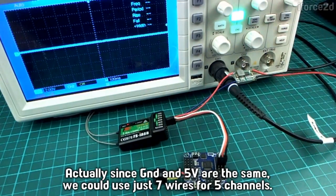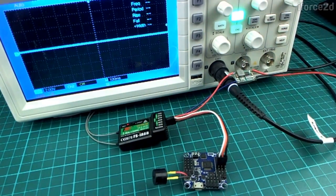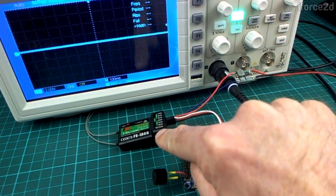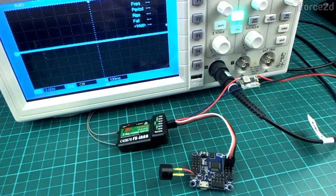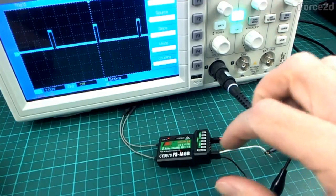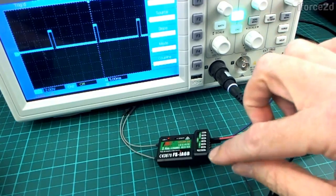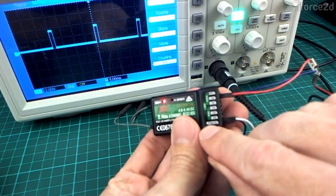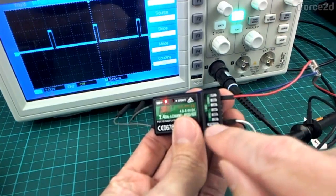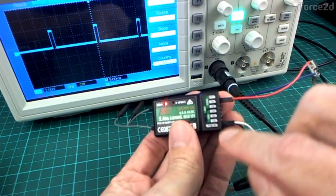So we have come up with other ways to do it, and that's what the PPM label on here is about. So we'll have a look at PPM now and see how that works. Okay, so I've connected up my oscilloscope again to channel 1, and channel 1 is the one that was also labeled with PPM. So I have to use this particular channel on this receiver to get PPM output.